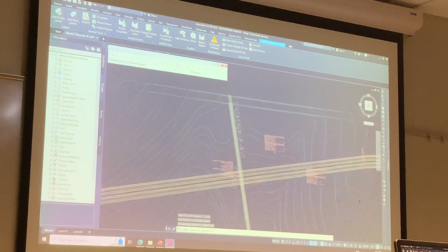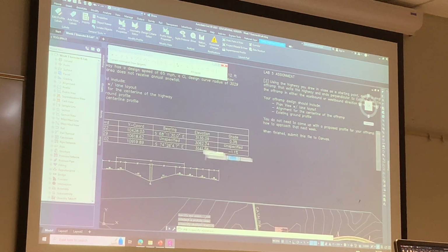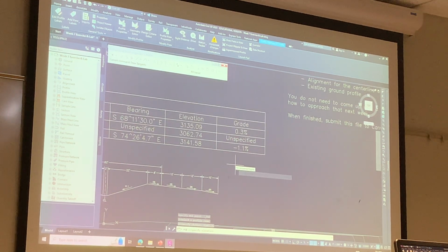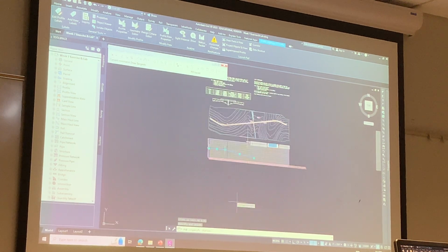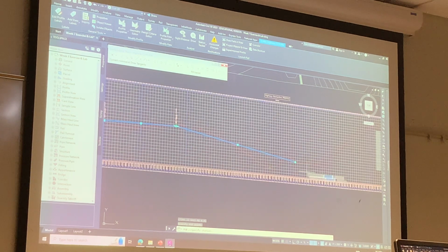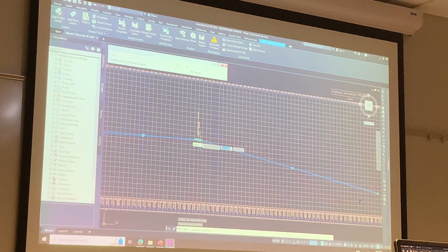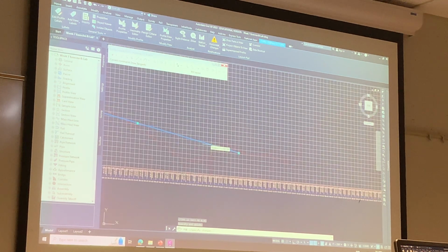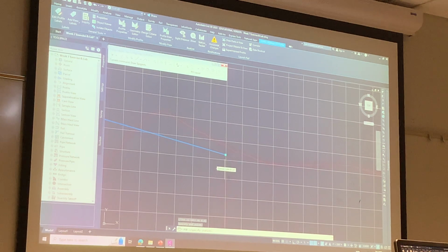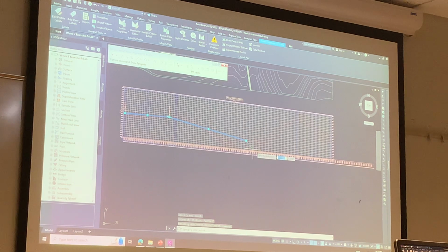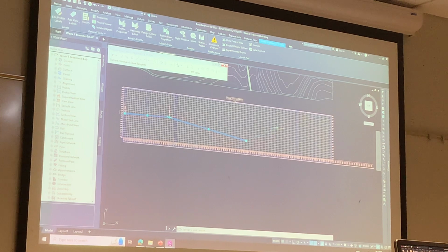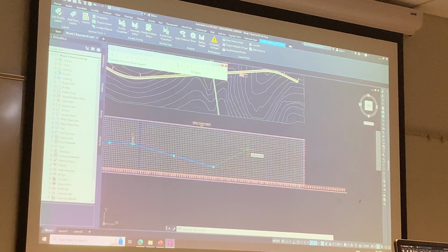Alrighty. The elevation will be 3062.74. Okay, so if we go back down to the profile, we'll see that it's drawing a point right there. It's connected to that profile line that I just previously drew, and it's connected to that point right here. You can escape if you'd like. And now you're drawing this line. We just continue to H3.